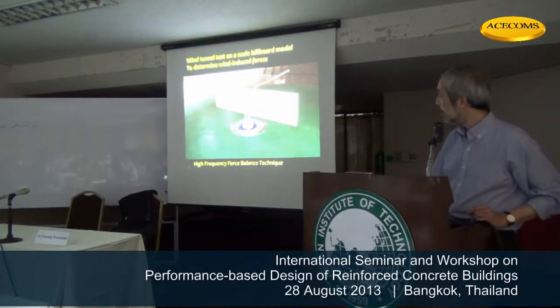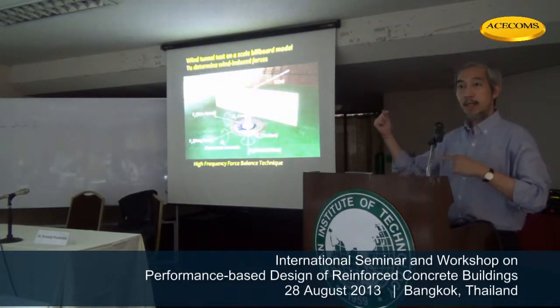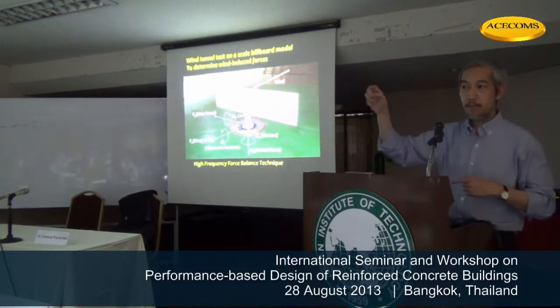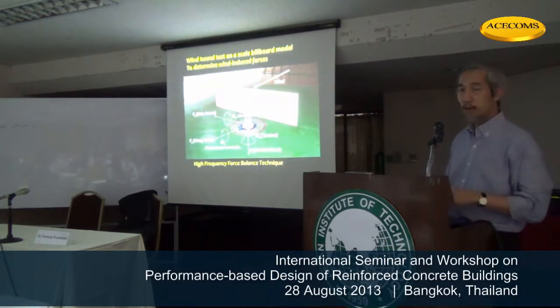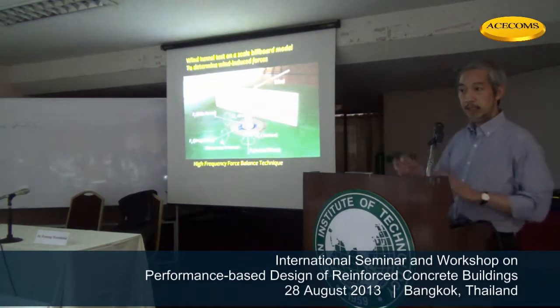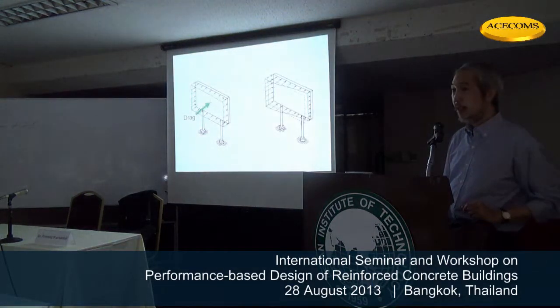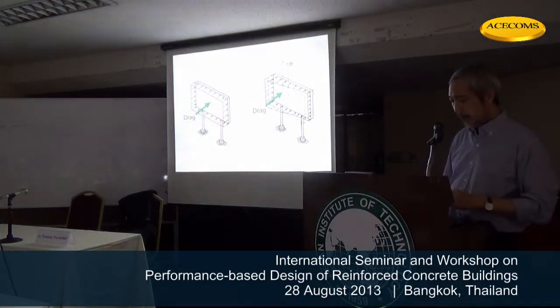This is a force sensor at the base, which allows us to measure the force in the wind direction, vertical, lateral, moment, overturning moment, twisting moment, and so on. Okay? This kind of technique will allow us to see the loading on the structure. So we can actually know at what condition it will produce very strong torsional effect.